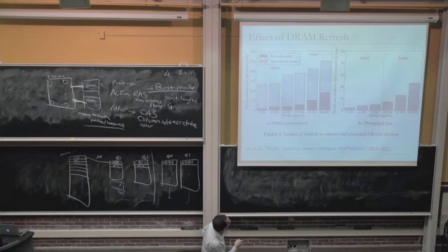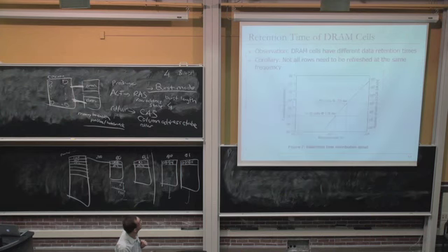And this is the performance impact of refresh, unavailability of devices due to refresh. So again, today, 10% of the time is spent for refreshes. So this is the performance overhead, if you will. But as you increase the size of the chip, 40% of the time, you're going to wait for refreshes. So this is not good. So we need techniques to fix this problem.